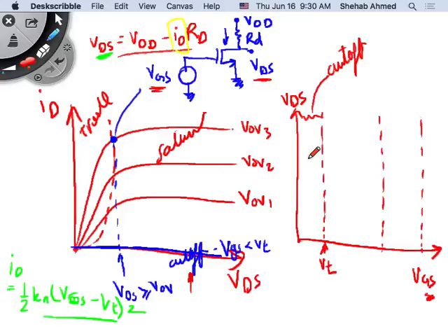What's happening there? And remember, that mode is when my channel width is not being changed, and I have a linear relationship between the current and voltage. That's this mode here, right? What is this mode? Triode. So this mode is when I have low VDS, and then VGS higher than VT. So it's somewhere in the intersection between this and VGS greater than VT. How much greater than VT? Does it really matter? As long as it's greater than VT, I'm creating some overdrive voltage.